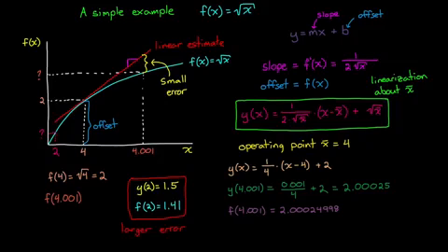So if that error is more than we can handle, we may choose to also linearize at the operating point 2, and then hand off between the two linear models as x changes between 2 and 4. Even though this example was simple, it ties in well with our tank example that we started with.